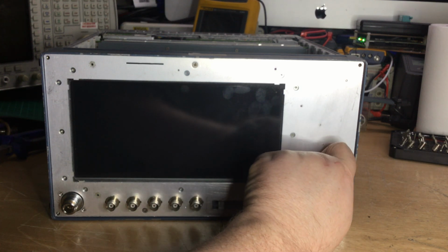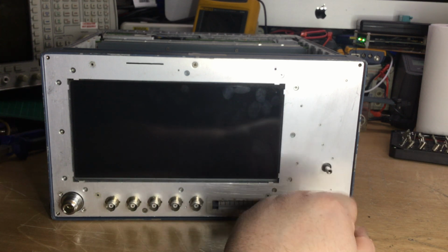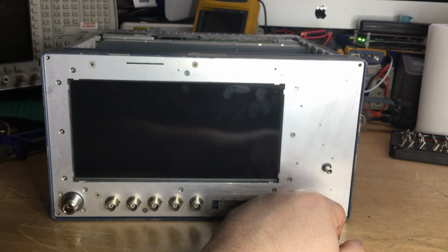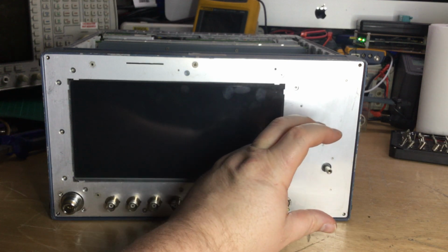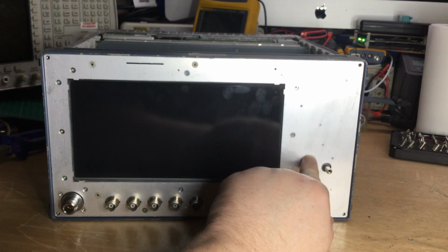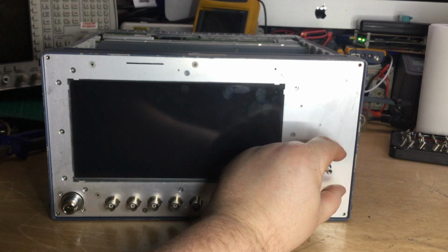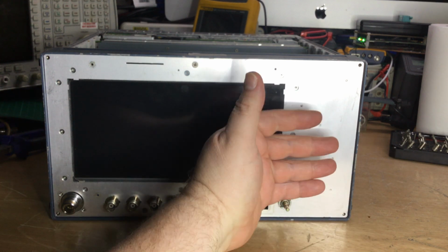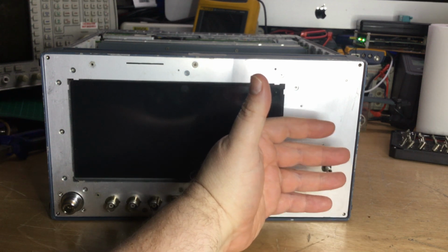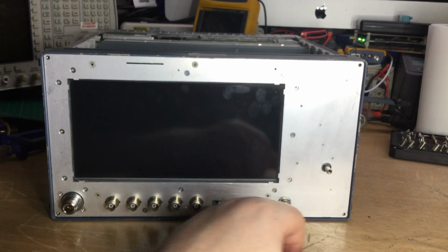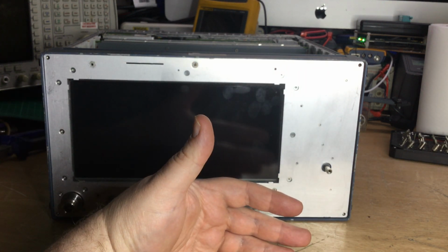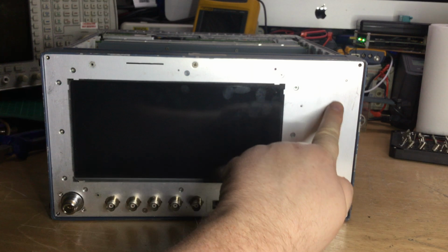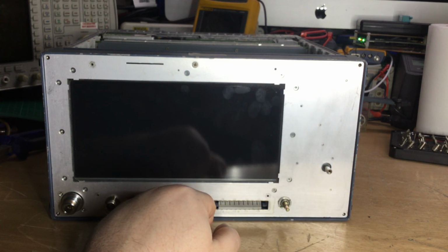I thought that the diagonal screws that I pointed out earlier on that PCB held that control board to the front of this test set, and it doesn't. It's just the body, the plastic bodywork on the Hall effect sensors for the spinner, the variable control, is quite large, and it was actually screws that held that together rather than fasten the circuit board to the front of the test set. So you have to remove the front and drop it down in order to then access the main screws that hold the PCB in, that covers all this area all the way around, in order to get at it.